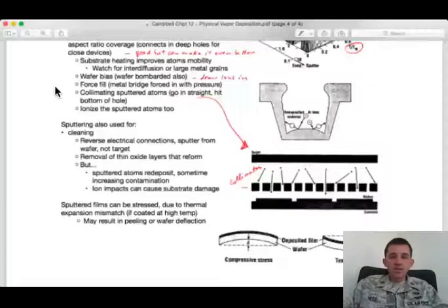The yield also increases depending upon what ion we are using to sputter with. We see here that you get a higher yield as your sputtering atom increases, which makes sense. Again, you're putting in more energy, whether you put that energy in via the velocity of the impacting ion or the size of the impacting ion. The kinetic energy is 1/2 mv squared. So you see here this kind of parabolic dependence. Here it's more linear.